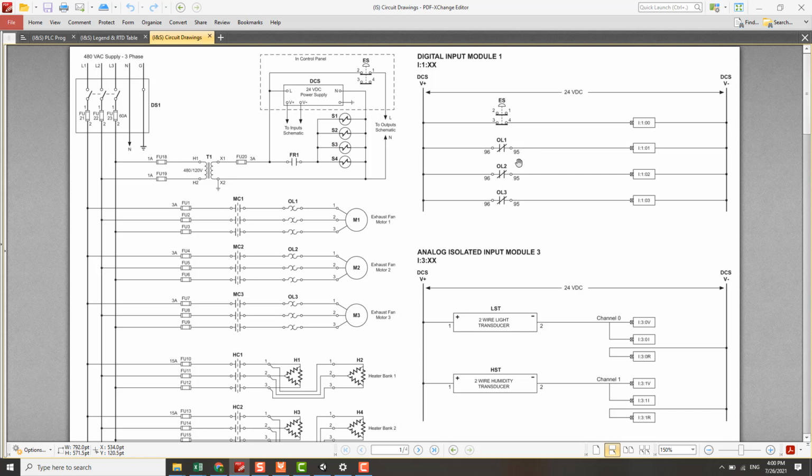Okay, we know that this overload relay auxiliary switch is most of the time connected as a normally closed circuit. Of course, I don't deny, maybe in rare circumstances it may be connected as a normally open auxiliary switch, but it is quite rare if ever. So if this overload relay 1 is open circuit, current cannot flow through this PLC input module 1 channel 1 to energize it. Okay, so it's possible. So we measure here.